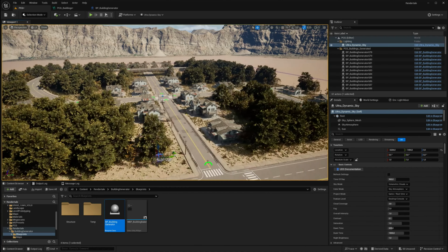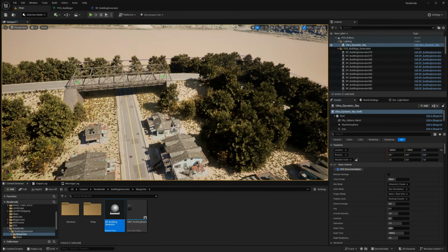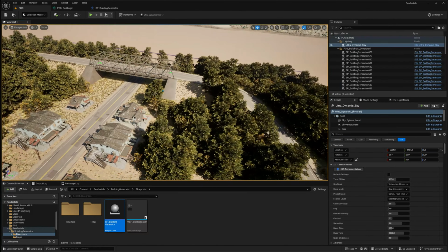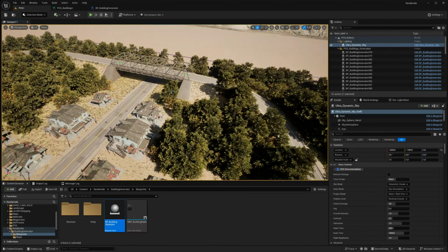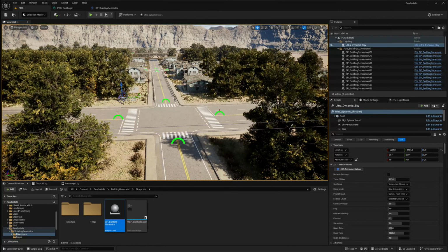The integration of foliage with the PCG-based building system not only enhances the realism of your procedural environments but also opens the door to creating fully dynamic ecosystems within your urban layouts. By tagging key actors, like buildings, you allow the PCG system to make intelligent decisions during generation. This prevents undesirable overlaps and ensures that vegetation only appears where it makes sense.